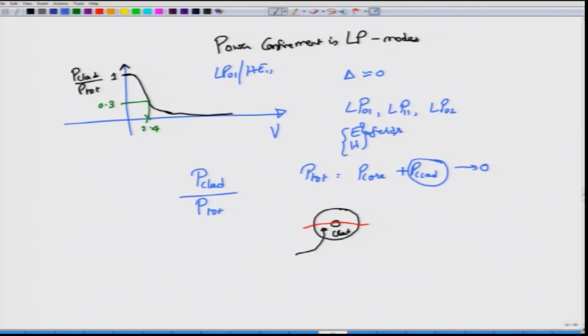Remember, its cutoff is around 4, and at that value the corresponding power or the confinement factor is almost close to the case for the LP01 mode itself. So, it will also start at around 1 and then come down like this. Okay. It would come down much faster here. So, I should better show that one. Starts at 1, but then it comes down rapidly for larger values of V. Okay. So, you can see that other modes also have this kind of behavior.